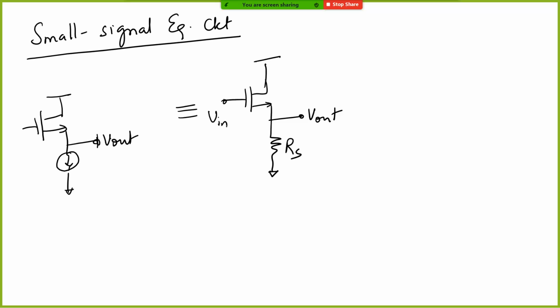All right. So here, of course, what we talked about, VGS is fairly constant. As V in increases, we looked at that negative feedback action. We said that this particular structure will keep ID fairly constant, and therefore V out follows V in.